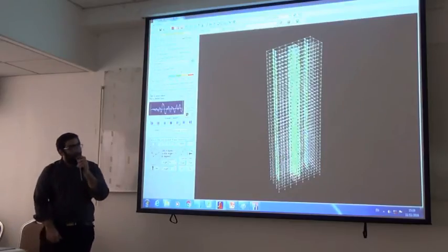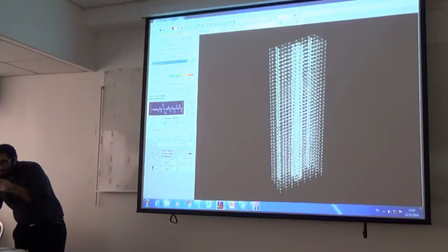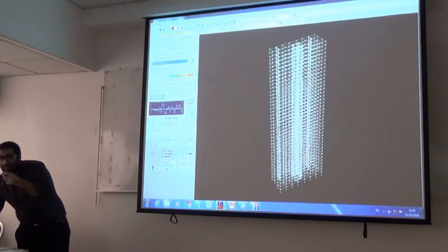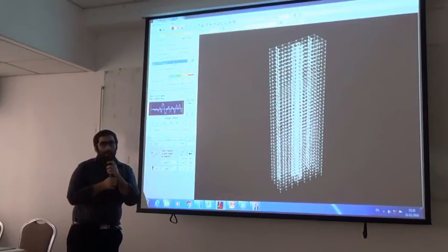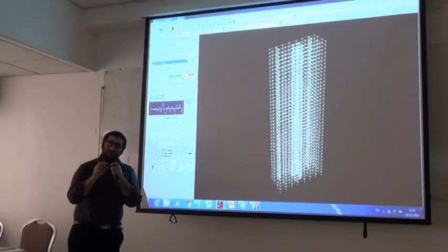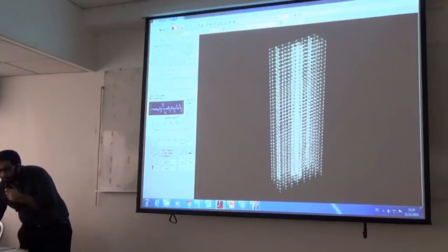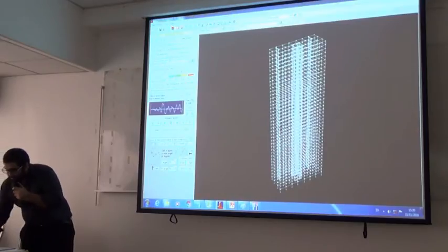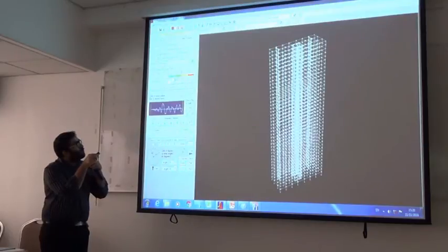Yeah. Okay. So now the other option that I will show you over here is the rotation in the girders. So I already spoke about the limit state. When we talked about the limit states of the girders, I already said that we have defined some limit state. Now, if we want to use that limit state to get the DC ratio, we can use it. I will show you the colored plots of the girders also. Now, you can see the numbers that are mentioned over here in the ratios that are the same in here. The light blue color corresponds to a DC ratio of 0.01.